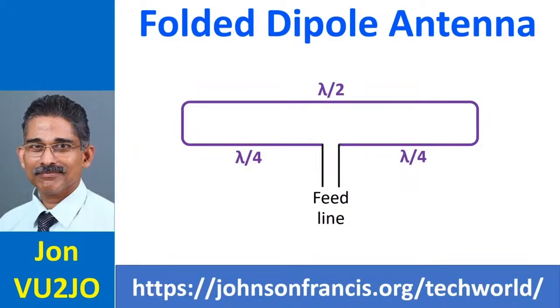Viewing from a homebrewer's aspect, it is technically more difficult to make folded dipole antennas as you have to bend the aluminum tubings usually used for such antennas at right angles twice on both sides. Hence, I am yet to venture into homebrewing of a folded dipole antenna. Folded dipole can be considered as a dipole antenna on top of which a loop of conductor is added so that it will be short-circuiting any direct current fed to the antenna, though antennas are typically fed with alternating currents.